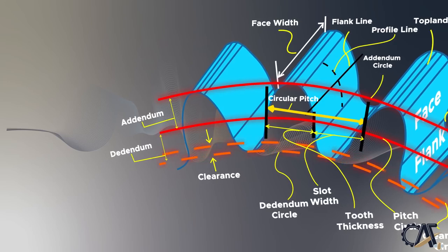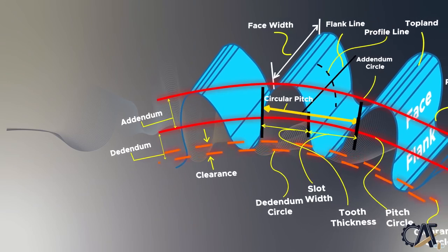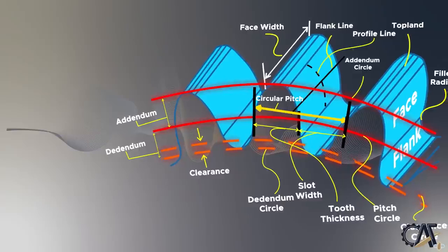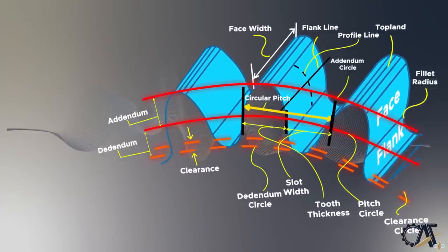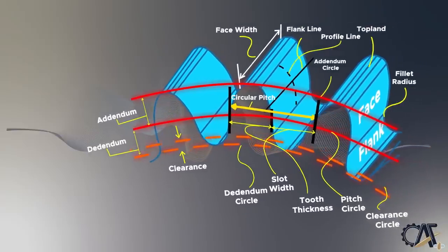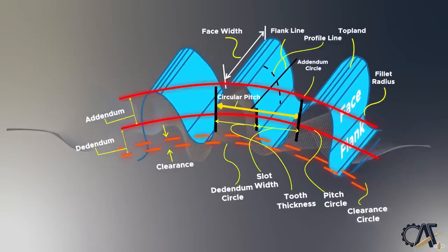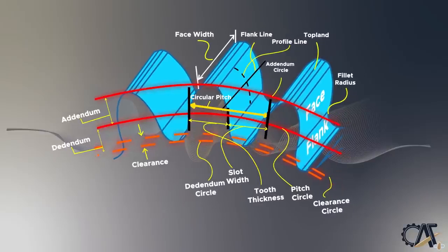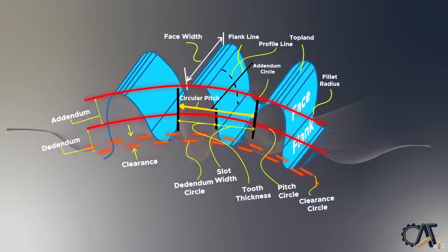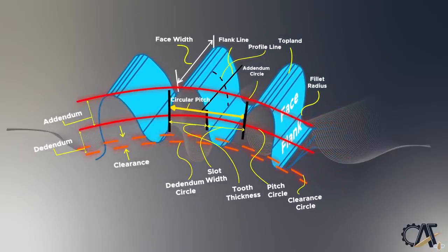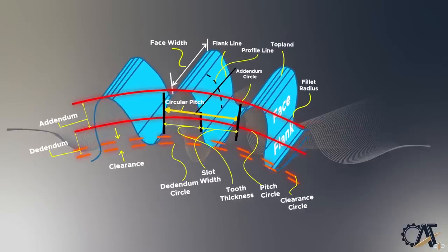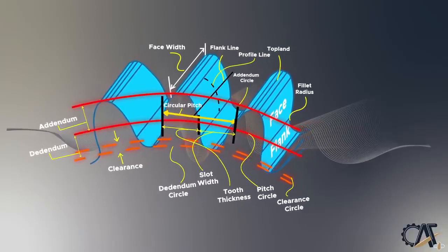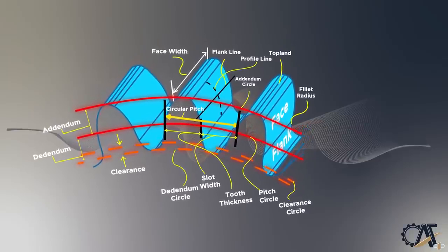For a gear to drive in a given direction and to transmit power or motion smoothly and with a minimum loss of energy, the contacting surface on mating gears must have the following properties. First, the height and the lengthwise shape of the active profiles of the teeth must be such that, before one pair of teeth goes out of contact during mesh, a second pair will have picked up its share of the load. This is called continuity of action. Thus, the height of the gear plays an important role here.